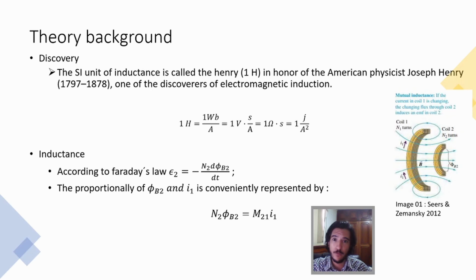The M is only going to be influenced by the size of the coil, the distance between the two coils, the number of turns these two coils have, and the amount of current in them. If I'm not wrong, that's all that is going to affect it. If you're talking about an environment with air or other materials surrounding it, you will of course have the influence of the material around it, because the material around the coil, which can be air, is going to directly influence the magnetic field, and thus the magnetic flux in the second coil.